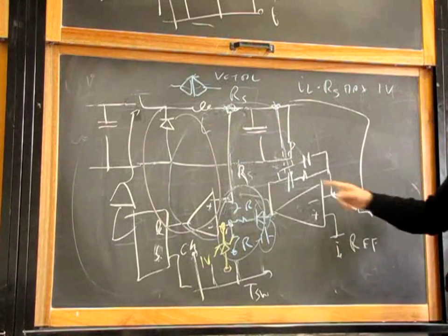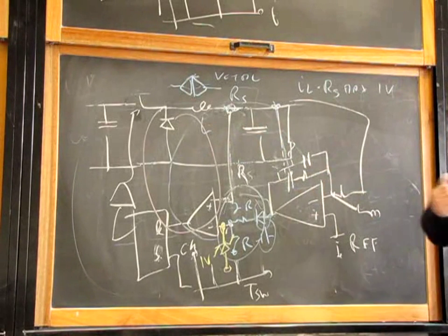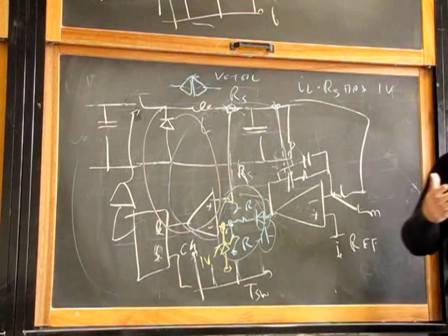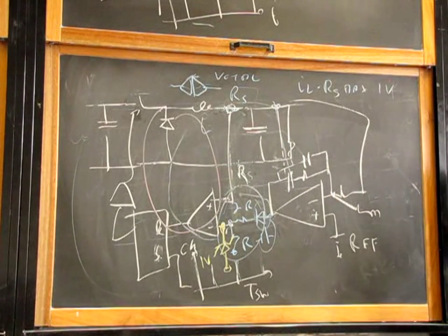And when it saturates, it means that these two capacitors charge to a strange, wrong voltage, and when you come back into linearity, you have to discharge these two capacitors to go back into linearity. If you implement a digital integrator, the phenomenon is called wind up, because it goes to saturation, and there are also anti-wind up systems for digital. Here you don't have the wind up.